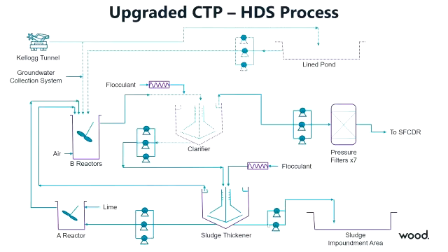We built the new rapid mix tank or reactor system where we conditioned sludge with lime, so similar processes as before, but recycled quite a bit more solids back into the process to start generating that high density sludge. The clarifier was incorporated into this process, but the sludge management system changed. We would continue to use this to generate about 8 to 10% solids, but we implemented a recycle system to bring it into a new 105-foot diameter sludge thickener where we could thicken that to 25% solids or greater.